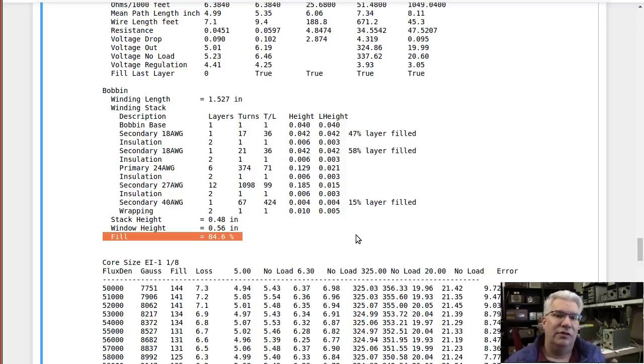When we design audio transformers, we have a bandwidth that we want to look at, and so we have to be very cognizant of the leakage inductance and the capacitance itself. And so we can't use the same procedure for doing audio transformers. We have to have a different one for that. Luckily, Wolpert has an audio transformer book as well. I'm going through that, and I'm going to modify this. I'm going to make it separate. I'm going to copy this and start again with one that's for winding audio transformers. And we'll go through that, and we'll be able to wind up our audio transformers and be able to predict performance. We'll wind up some of those, and then we will actually measure the bandwidth on the bench here.